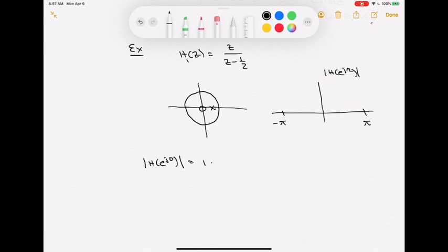And then I'm going to multiply that by the distance from the 0 to the frequency of interest. Frequency of interest here is at z equaling 1. That's my cap omega equaling 0. And since the 0 is at the origin, anything on the unit circle is going to be 1 unit from it. So the 0's distance to that frequency, or any frequency, is going to be 1.